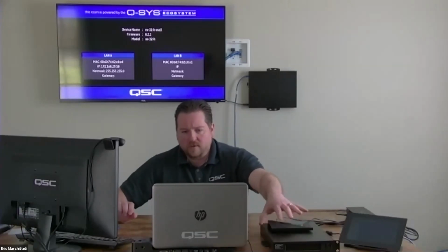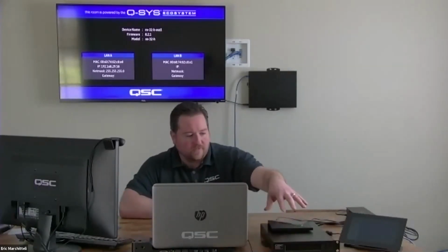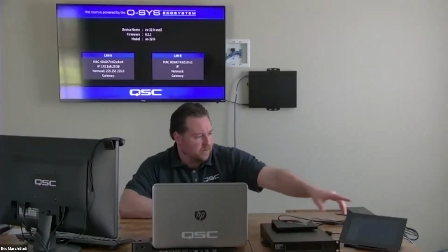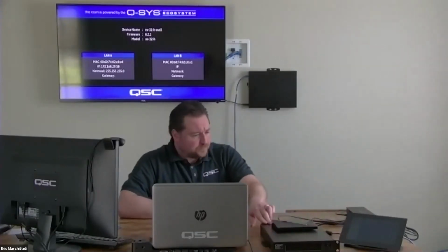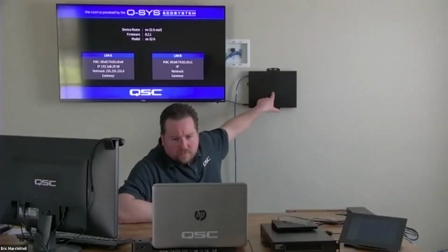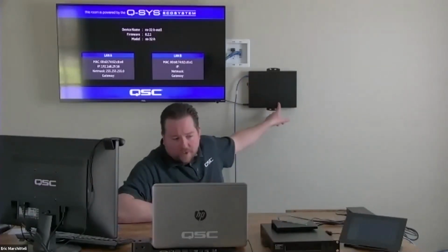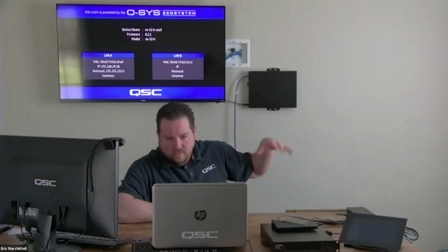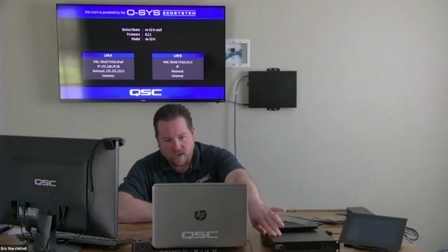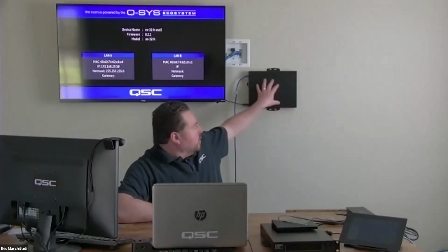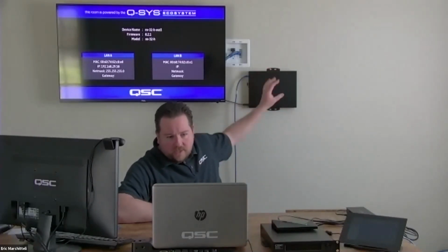All right, no more questions. Take it away, Eric. Okay, so the next thing we'll do, we'll add the video. So you see here, I have two NV32s. I have one here on the desk, which I'm going to use as an encoder. So I have a couple sources here. I have a media player and then another media player down there. And then behind me, I have one mounted behind me, which is connected via HDMI to the display, and that's going to be our decoder. So obviously, they're right next to each other, but in the real world, one would be, say, under a conference table or a lectern, and then this other one might be up behind displays or up in the ceiling at a projector location.